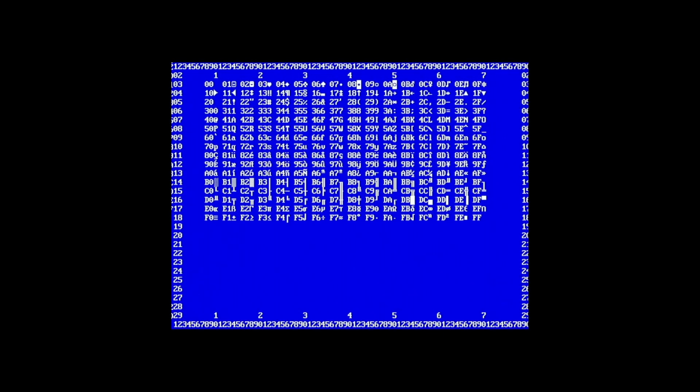I've tuned some of the timing signals for the CRTC. So for this display, which is 30 lines down and 80 characters across, this actually fits pretty well on both the LCD monitor and on this video capture card. But you can see that there's about half a character at the beginning and about half a character at the end, which is not quite right. So what we're going to try and do here is to get it so these fit properly.